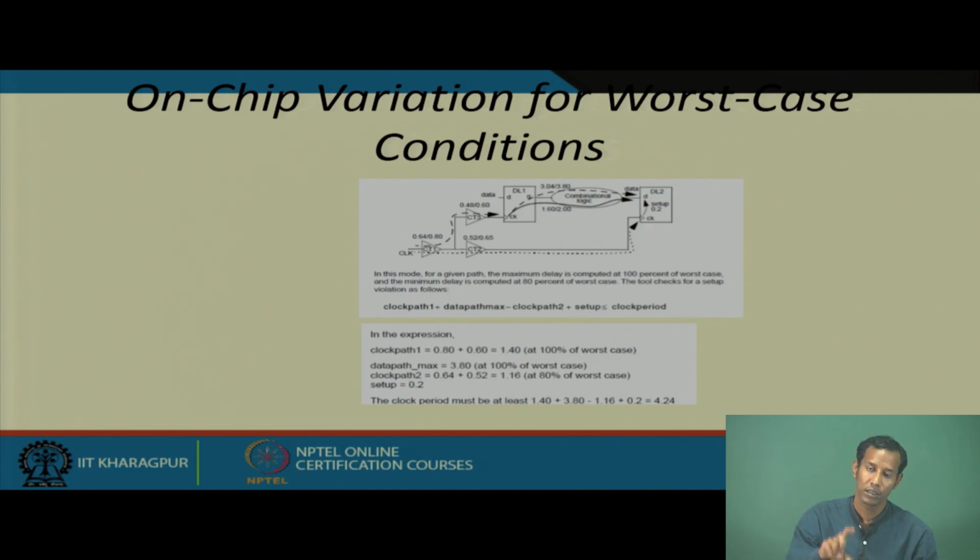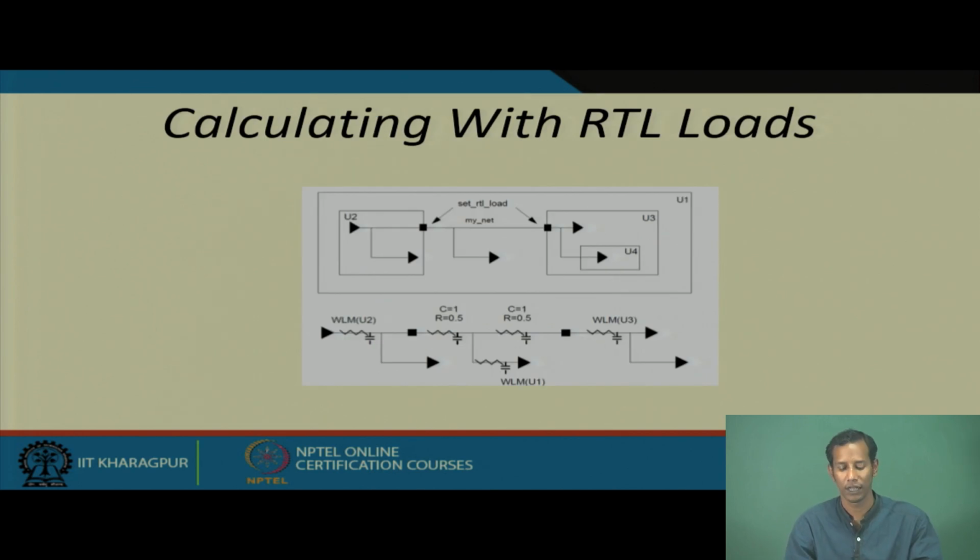Now suppose you run that tool for timing analysis and you see that for some paths you are getting some violation. At that time you can identify that path and calculate manually, with the delay information, what changes I should make to overcome the violation so that my chip works perfectly fine. For that reason you have to know what particular aspects to calculate for the hold check as well as the setup timing check while doing the timing analysis.